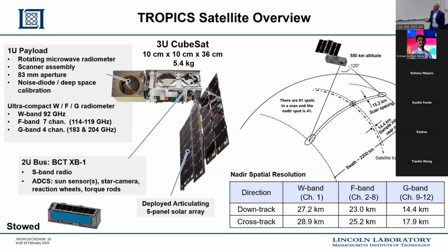Okay, so a little bit of detail on what these satellites are and how they work. They're really an engineering marvel, I think, how small these things are and all the capability that we have been able to put in these things. The solar array is moving as the satellite is orbiting to track the sun to get the power to the spacecraft systems and the payload. The payload is turning, the bus is rolling to keep the array on the sun. So there's all this motion on this little satellite.